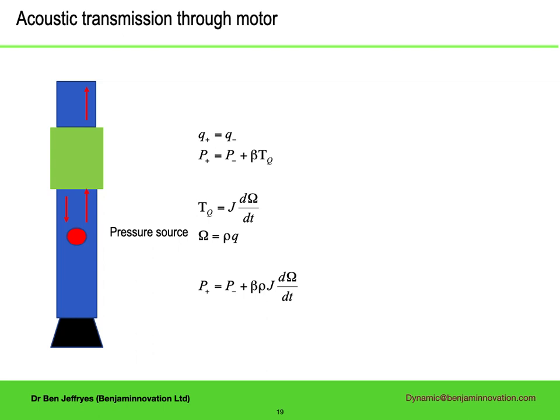Something else with a pressure drop that sound may have to get through in a drill string is a motor. There are a number of occasions when MWD sources are placed below motors. In casing drilling assemblies there is no option, but also when running rotary steerable systems below motors, the MWD system may also be placed below the motor to get the surveying measurements close to the bit. What happens to the signal in these circumstances?